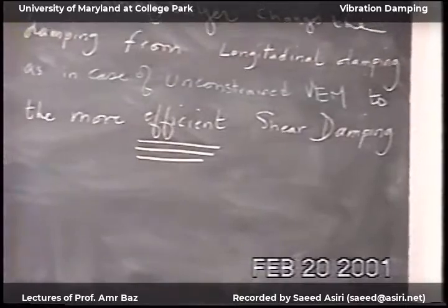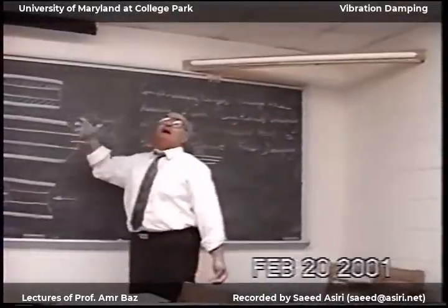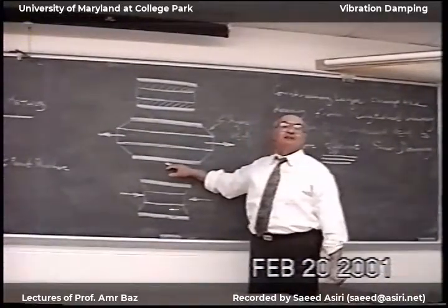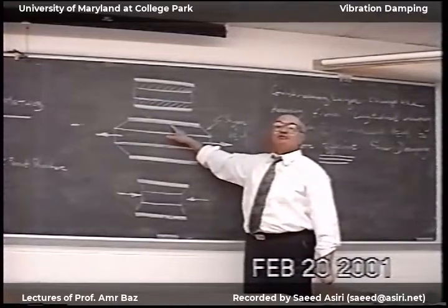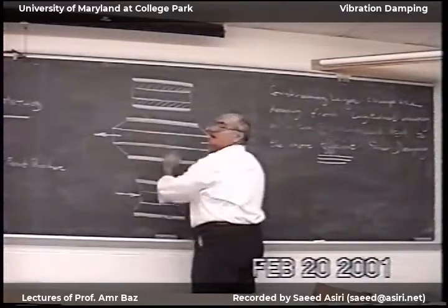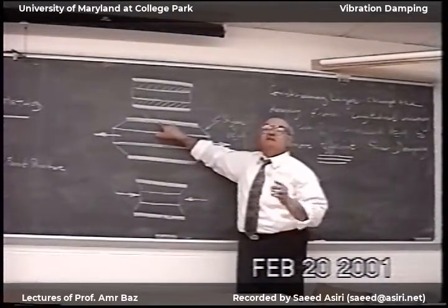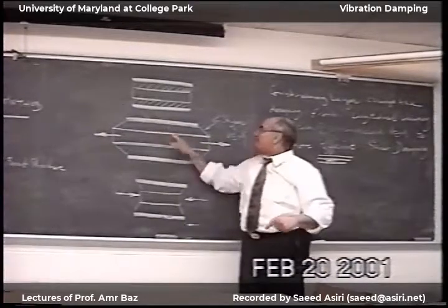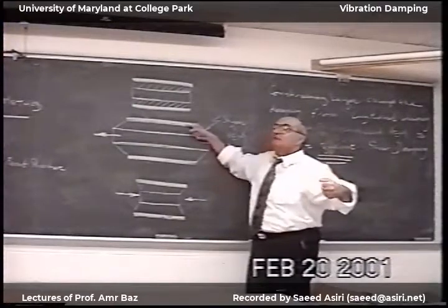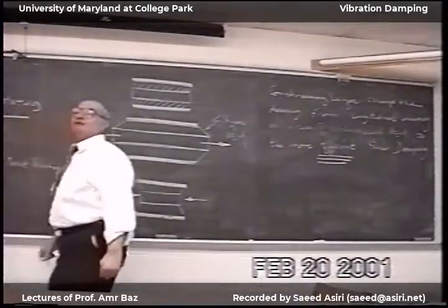Okay, of course, we could make the top layer an active constraining layer. So the active constraint layer, when I see this is stretching, I can make this shrink more. So if I take the top material and instead of just any material I make it piezoelectric material, take the structure response, feed the signal to the top, I can make this more effective.